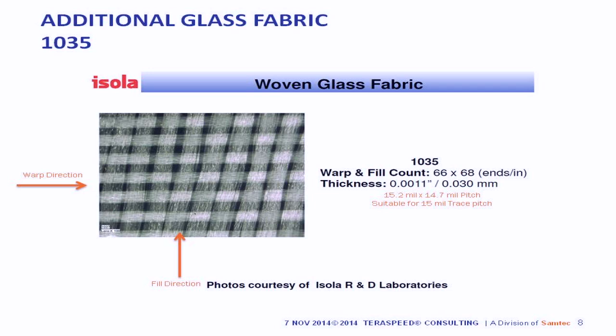So now you can see that if a trace is running in the warp direction, it has fairly uniform properties, but in the woof direction, or the fill direction, it's crossing those fibers at a diagonal.